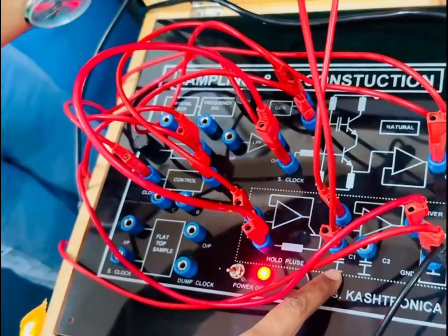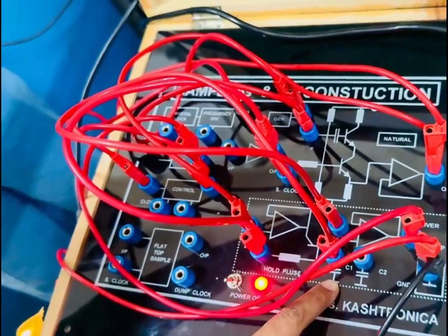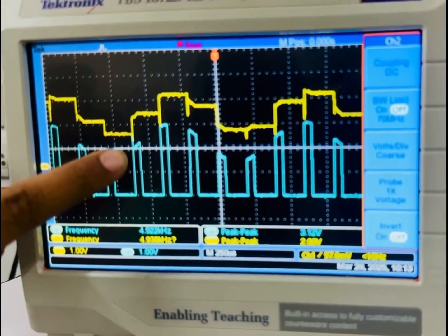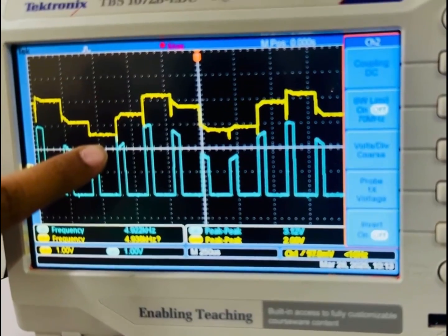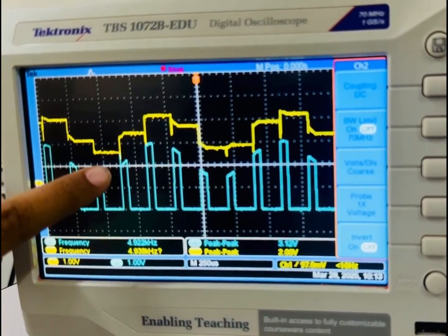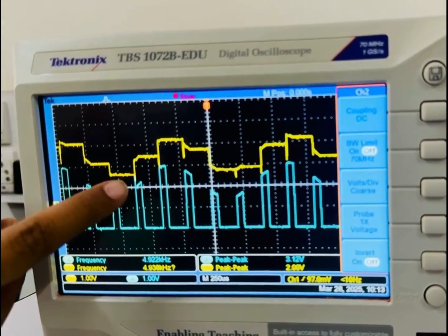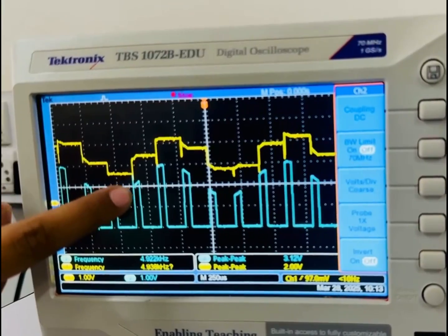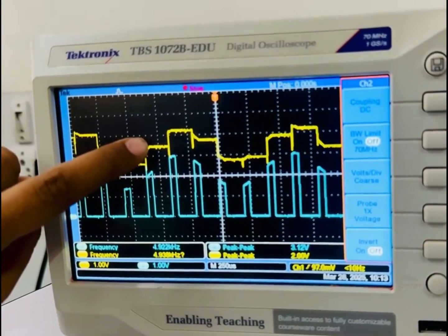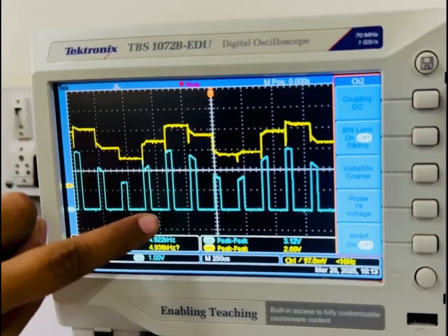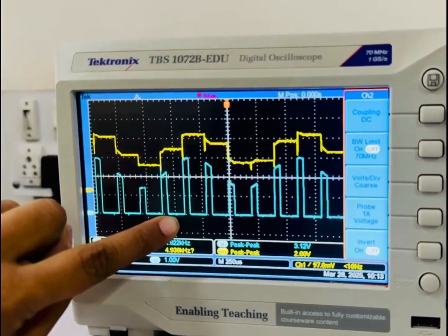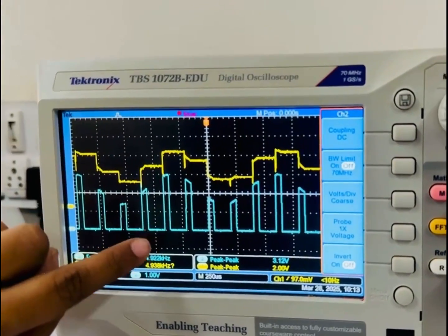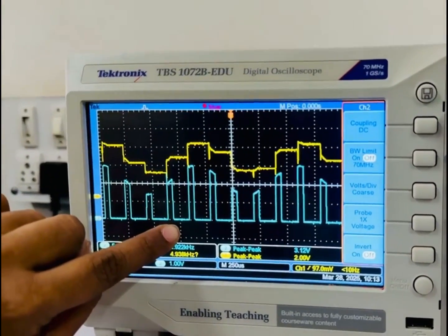So the capacitor C1 will now start charging to the amplitude of the sample. So if you look at the waveform, see here the pulse is available, the sample is available, so the transistor is on and the capacitor gets this sample amplitude for charging. So the capacitor starts charging towards this sample amplitude and it will follow the amplitude changes in the sample. Now between two samples, the level of the voltage is 0. Similarly, these are two consecutive clock pulses and in between two clock pulses, the voltage level is 0.